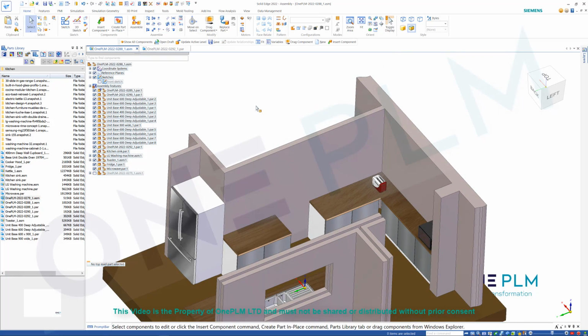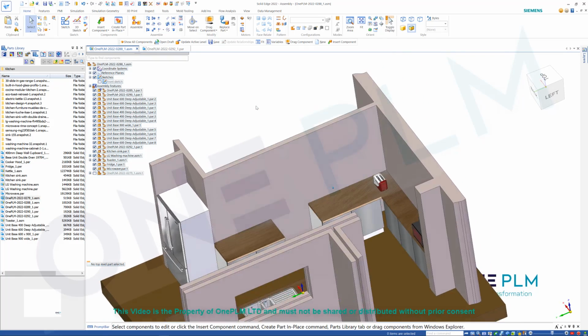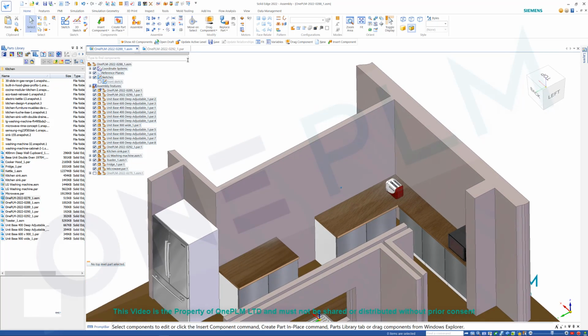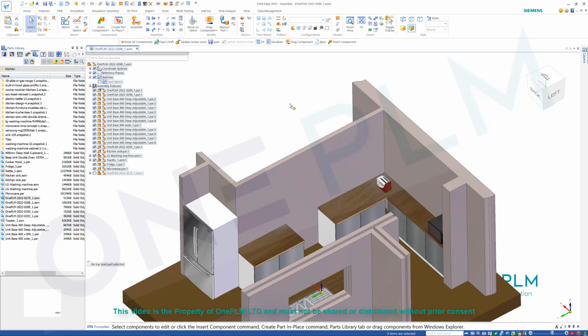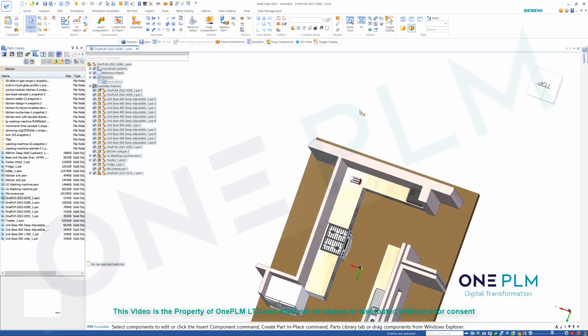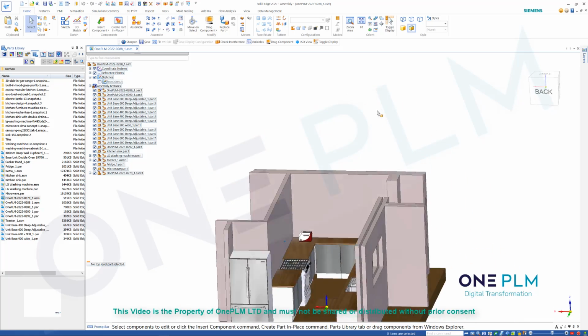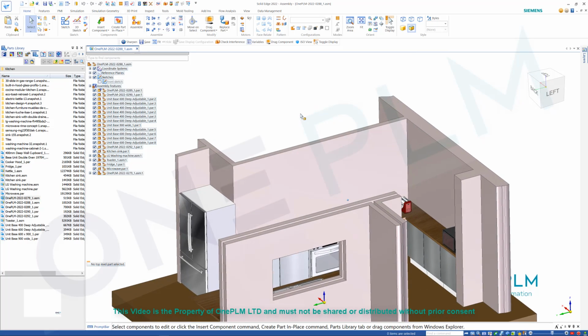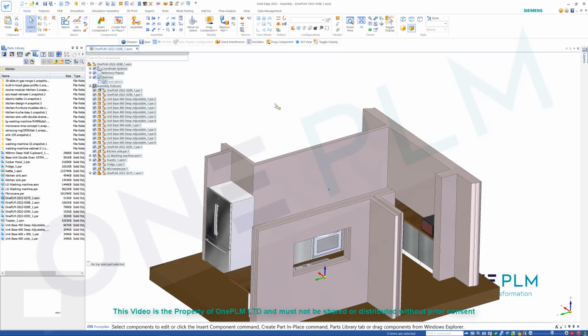As long as we update the assembly, so we can use Alt-U to update, we can see that it has worked nicely on there. So we can close that part now. And we can do a right click and do a show all, and that will bring all those parts back. Now we've got that looking pretty good. What I'm going to do is speed up this next section.